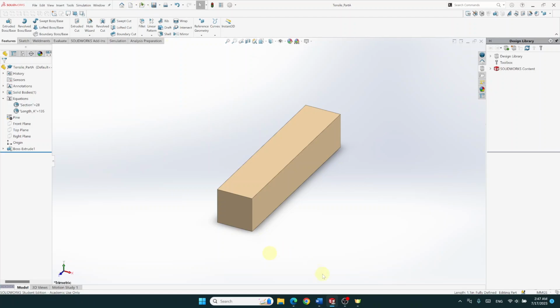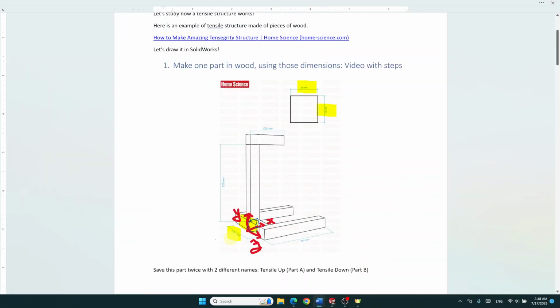Don't forget to save. So I come back on my dimension, so I did the little part on the bottom. Now I need to add the front and the back and the up and the down. And you see we have 3 more dimensions to add. I will add them one at a time. Let's do this one, 180, and I can do both at the same time. So I will add a section in the plane YZ, and I will extrude it 190. Okay. So I draw the section there, and I extrude both of them together 190.